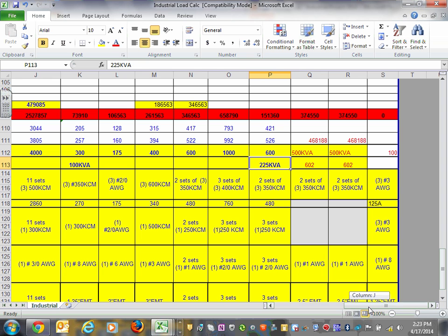After you do that, any comments, guys, about the kVA for the receptacle panel and the kVA for the 28120 bus duct? All the standard sizes of transformers are right here, or you can go to Cutler-Hammer, Square D, or any one of those guys. They can get you this information. It's as easy as picking up the load in kVA and going to the next standard transformer. Remember, it's based on after you add the 125 on it.